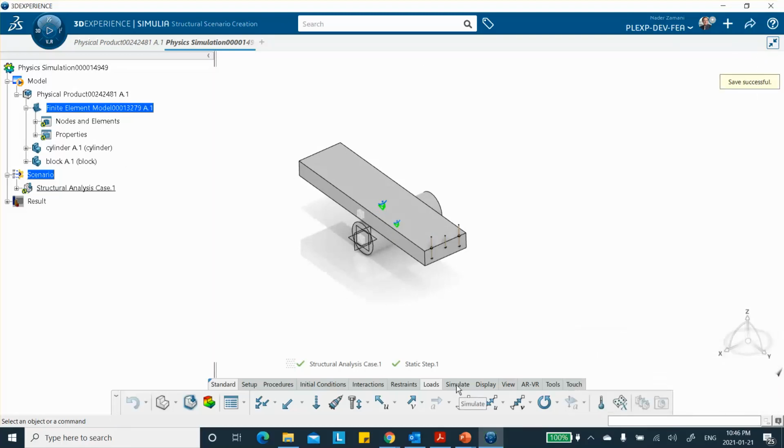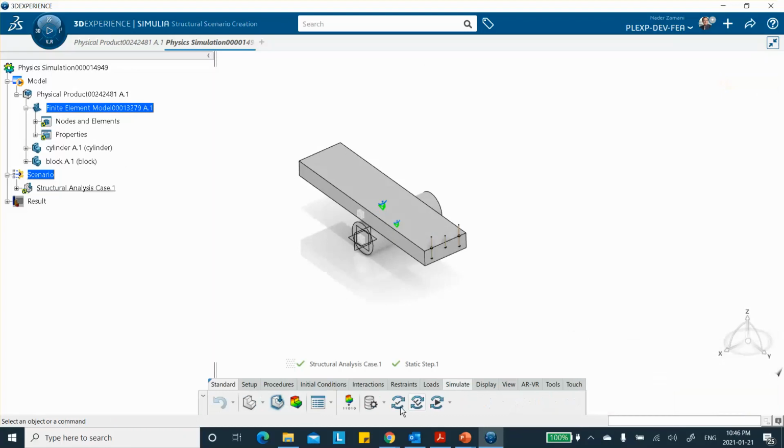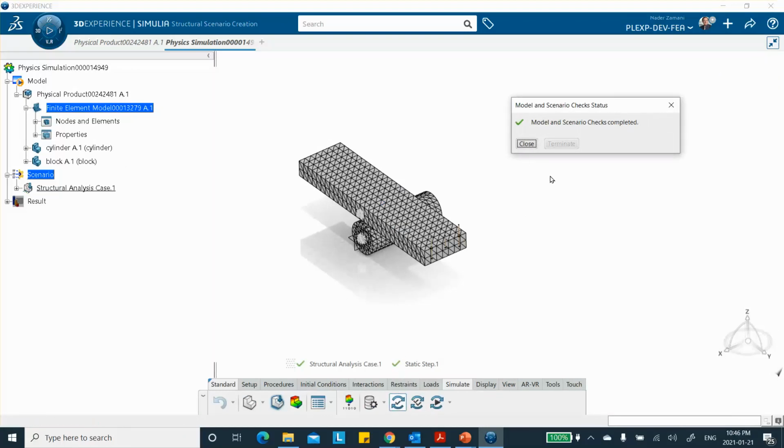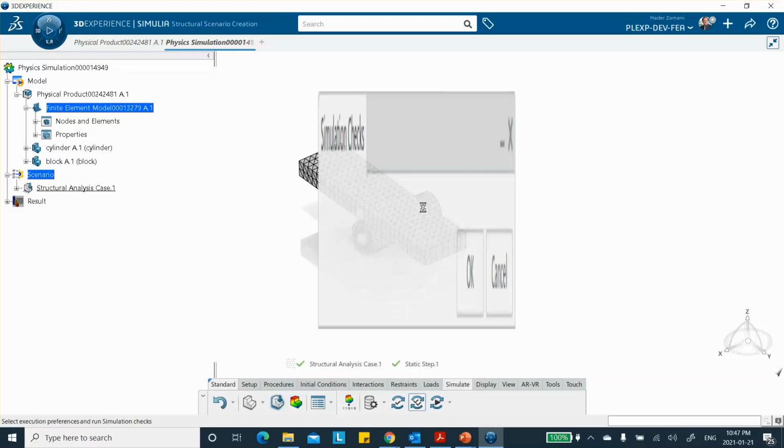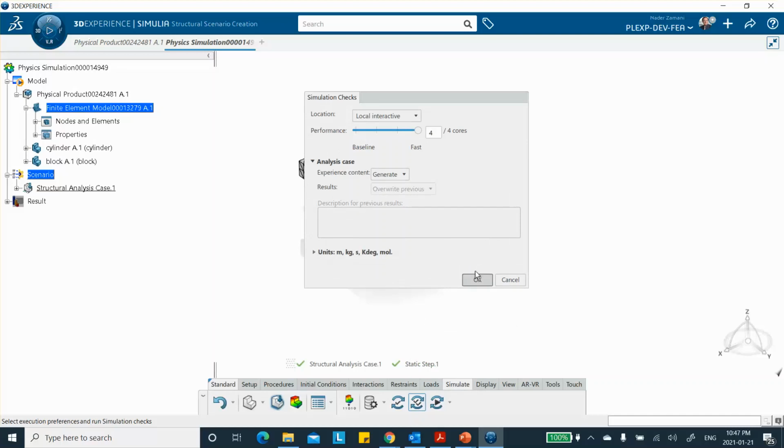We go to the simulation. Let's do some checking here. Oh, yeah. You know what's going to happen? This is going to go through that because we haven't defined the interaction, contact interactions. That's okay. Let me show you. That's good. Because we have a problem here. I want to show you that if you forget contact, it's going to work, but it's going to go through that.